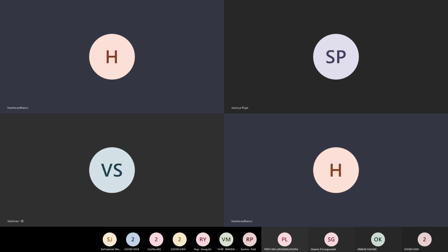Therefore, the soil particles are uprooted from the soil mass, and the soil starts acting as a very viscous fluid. So quicksand is not a type of sand, it is a condition where the pore pressure is greater than the total pressure, or the hydraulic gradient is greater than the critical hydraulic gradient.